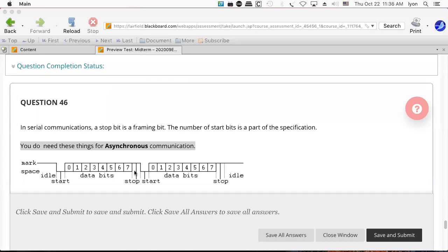It needs to have that because it'll have an internal clock that resynchronizes based on the bit clock window coming in. So that's what the baud rate is all about. It's how many bits, or actually how many symbol changes you're going to get per second. And we need to know where to do our sampling. We want to sample in the middle of each one of these little windows in order to make sure that we can know whether we're getting a 1 or a 0. If we're off, we're going to have a framing error.